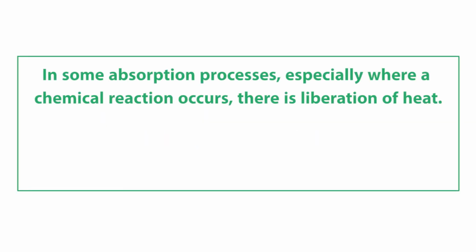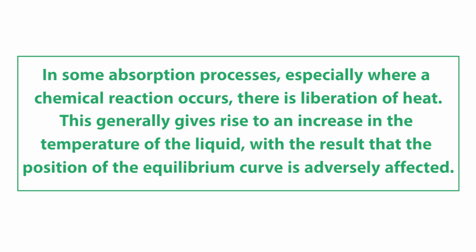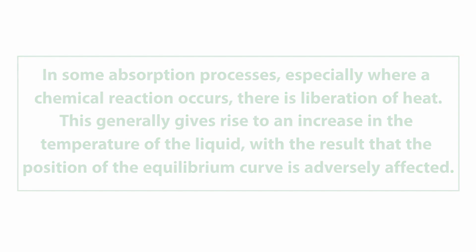Absorption accompanied by liberation of heat. In some absorption processes, especially where a chemical reaction occurs, there is liberation of heat. This generally gives rise to an increase in the temperature of the liquid, with the result that the position of the equilibrium curve is adversely affected.